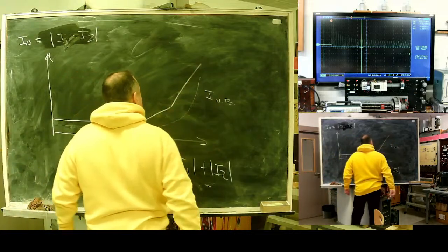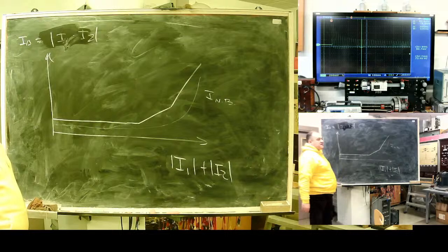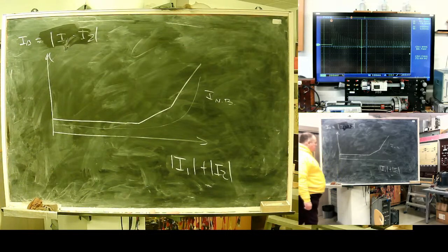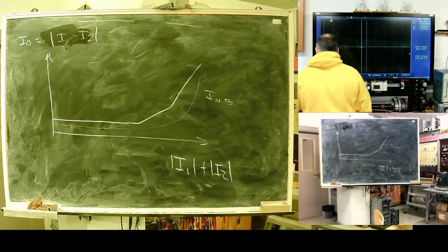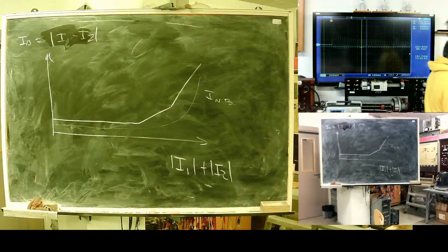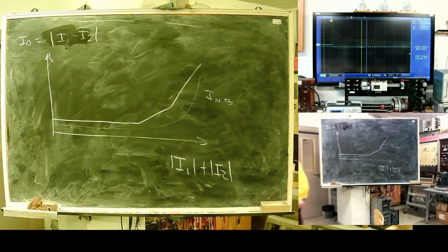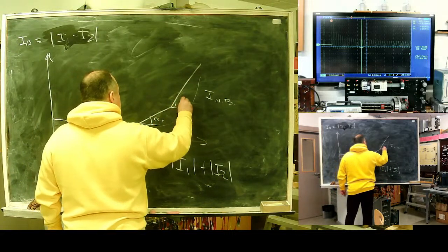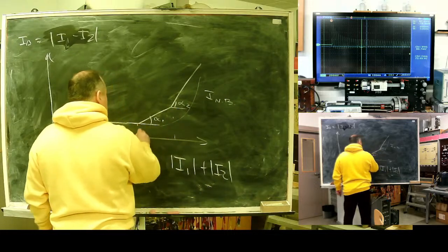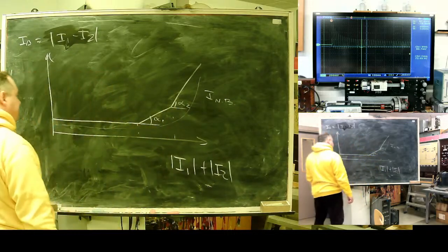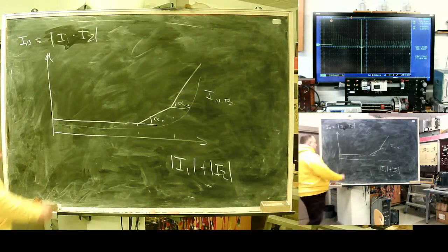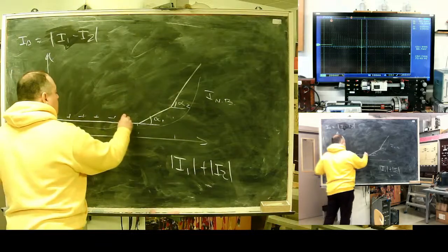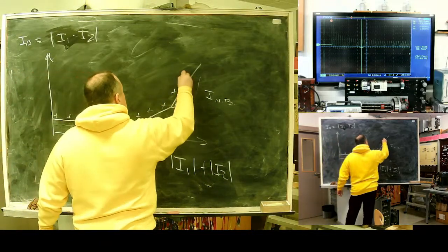usually incorporate a characteristic like this, three straight lines. It approximates well, and this kind of design with straight lines is chosen to reduce calculation burden, to increase performance, reducing operation time. Usually it's set with two angles and two operation points. It's the so-called stabilizing characteristic. For digital relays, it's actually an industry standard.